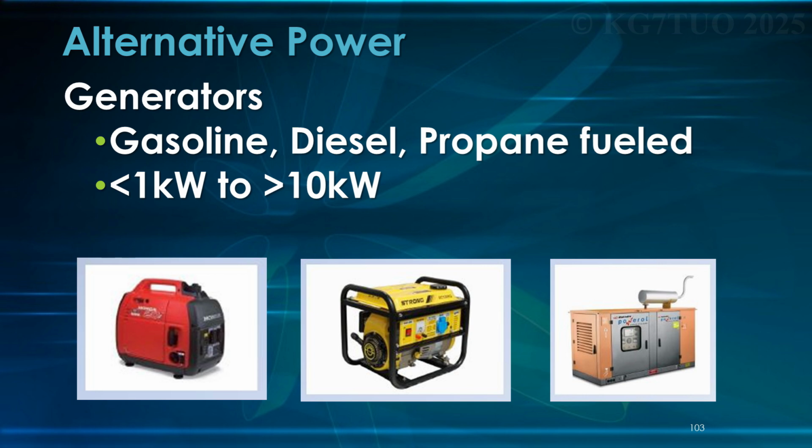What do you need to run a house? Well, it depends on what you want to run. I've got a big inverter that I put in the back of my Chevy Volt. I plug that into the house, and I've got a maximum of about 2 kilowatts that I can run off of that at 220 volts. I can run pretty much anything in the house, but I can't run them all at the same time.